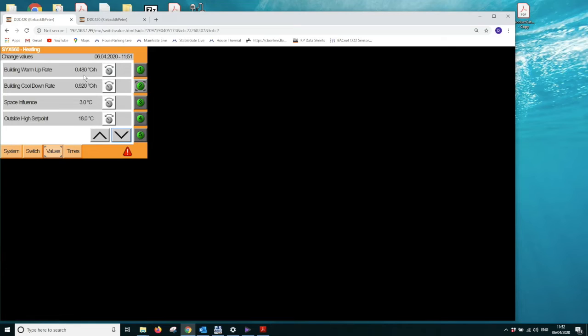For example, if the Optimiser is looking to heat the room to a set point of 22 degrees, but there is an underfloor heating circuit in the building and there is a thermostat controlling the underfloor heating, and the thermostat for the underfloor heating is set to 20 degrees. By that rationale, the heating for the underfloor heating would turn off at 20 degrees, and the optimizer would not be able to achieve the target temperature of 22. The optimizer would therefore carry on coming on earlier and earlier in order for it to achieve its target set point.